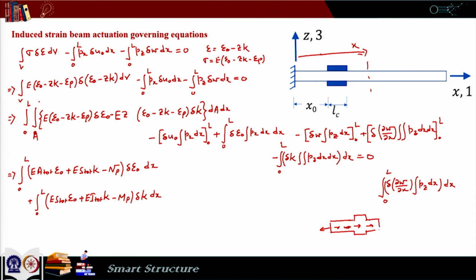Please do not be confused, it is just to show any force, these directions do not matter. If I sum up these forces, that force is equal to the negative of this force n for equilibrium. So, integration of p x gives me minus of n, and similarly integration of p z gives me the shear force V. And p z when integrated twice, which means when shear force is integrated once, gives me bending moment m.